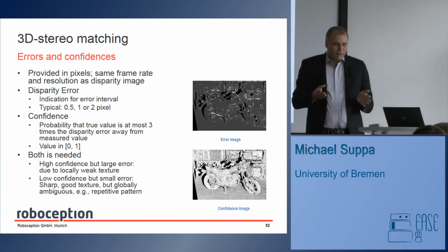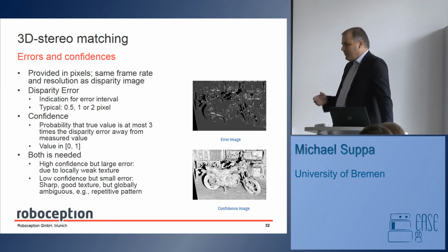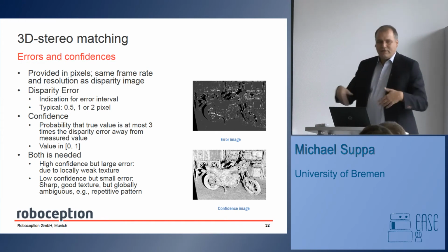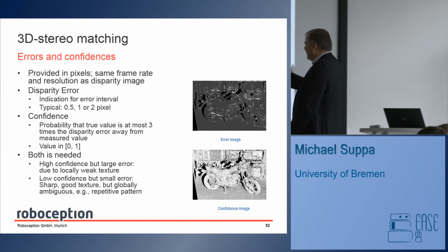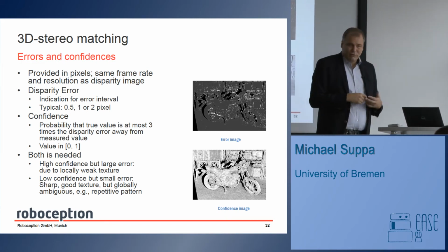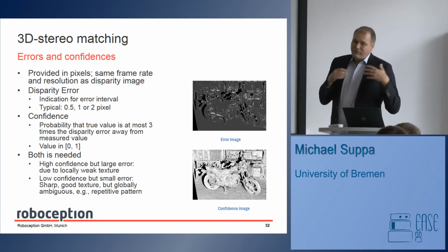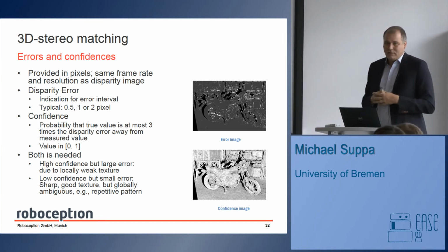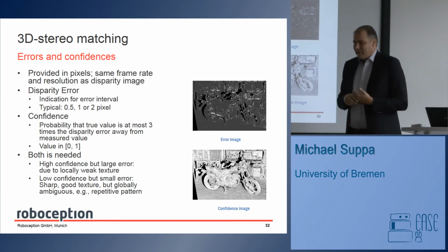This is when you have local texture that is kind of weak. So basically, the probability value or the confidence value is kind of an assumption about what you see in the scene. It has nothing to do with the statistical value that you can compute ahead of time. So you're using a little bit of what you see in the scene in order to interpret your data, which you always would do. But for stereo, it's nice to do, and especially in that algorithm. For laser and other sensors, it may be more difficult because you somehow have to figure out how to get to such a value.